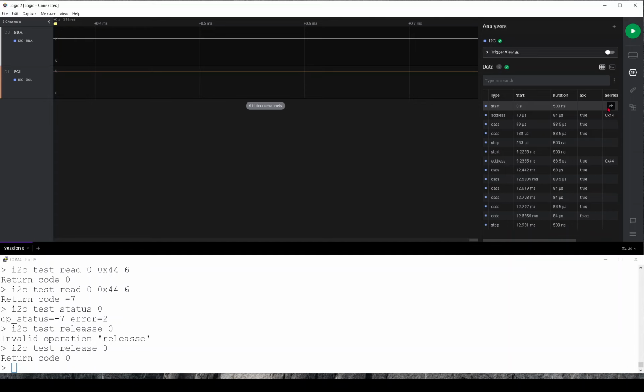If I were using this sensor chip on a product, I would put a lot of thought into this, because in software systems, things happen. And especially software systems that run 24/7 for days and months, things happen and you don't want to get stuck like this. So if I were putting this into a product, I would think about how from software I could recover from this condition without having to maybe even reset the MCU.